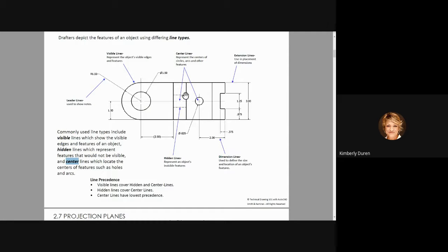But what about in the side view of a hole? I couldn't tell that this is a circular cut except that I have this, and this is called an axial center line. So we have a bullseye or top-down way to show the center line. And we actually dimension to those center lines. Never to this little center point, but these extension lines. Even over here, you see those gaps are maintained around that plus in the middle. So this is an axial center line.